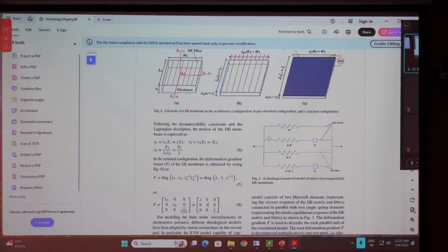That consists of a Maxwell element connected in parallel with a spring. I also told you why I have considered the Zener model. There is a specific reason. We could consider a simple Maxwell model, but the Zener model can take both phenomena into account effectively. It is the simplest model that takes stress relaxation and creep into the picture at the same time. Getting my point?